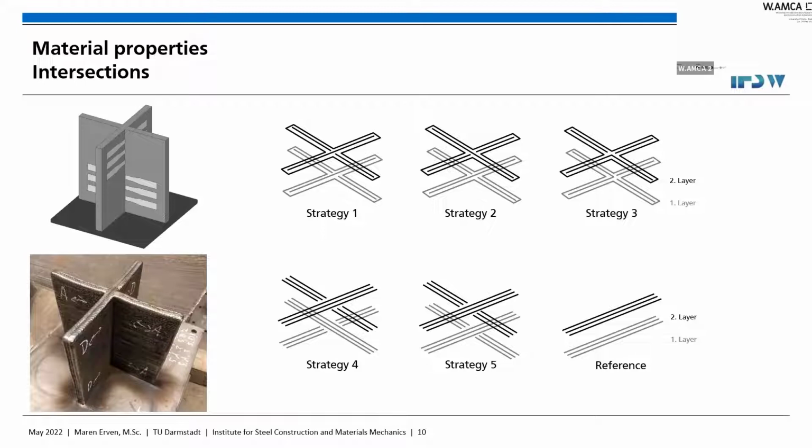And is it visible, or do you have a specimen? Could you detect it? Actually in that part, in the middle, there were holes and voids, or pores. But there it doesn't crack. Right, like here. After doing this tensile test, just like the normal tensile test, I also did some tensile tests on some failure specimens, and there I used the DIC. Then I thought, okay, I should use the DIC also for these specimens to see how the strength and the Young's modulus, the elasticity, are distributed.